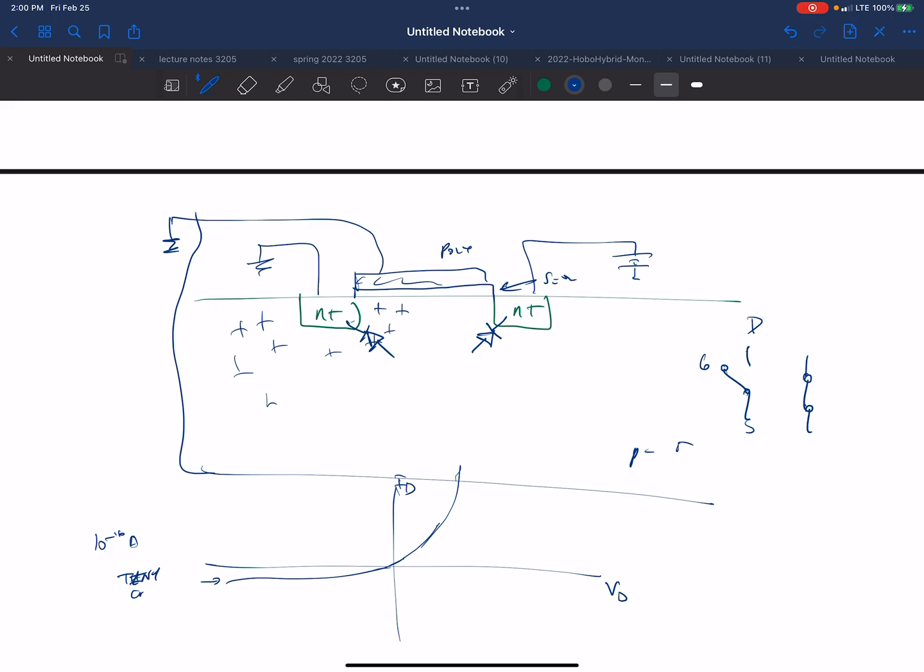If you look at the slides, this is what the stages of a MOS transistor look like, if you get into detail: accumulation, depletion, inversion, and inversion is when you are on. Everybody with me? By the way, this whole thing is pretty quick. When you turn it on, from 0 voltage, pushing these guys away, you're talking about picoseconds, something like 10 to the minus 12 seconds.